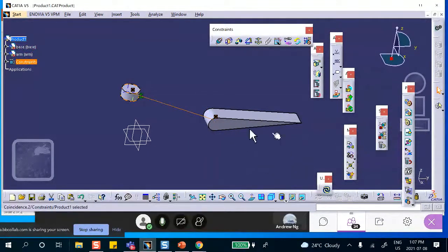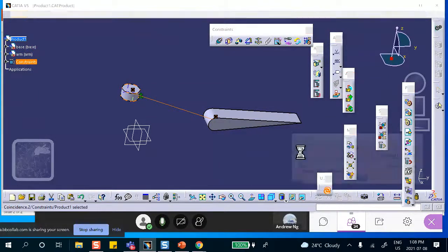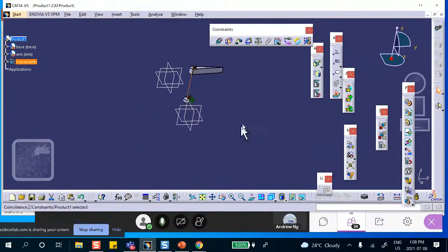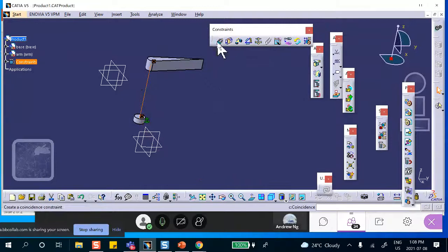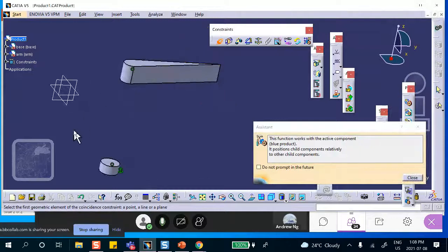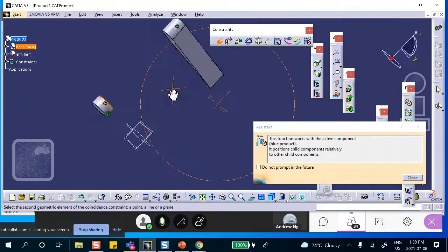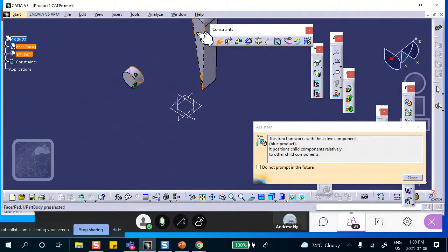And update. By the way, you can activate update so that it automatically does it for you. You don't have to click on it, but you have to go to the tools, icons, tools options, etc. That's fine. Now notice that it made the coincidence, this axis and that axis, and then coincidence. I want to show you something here between this face. And remember, I have to rotate this and take the bottom, okay?